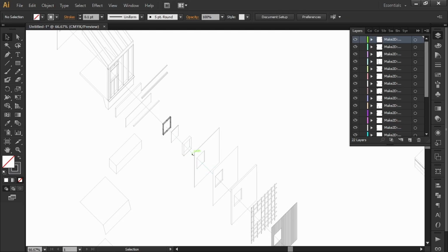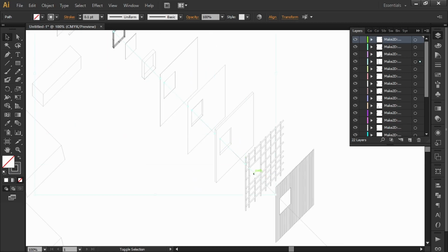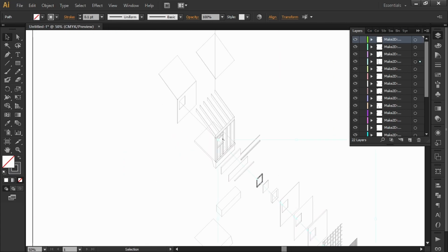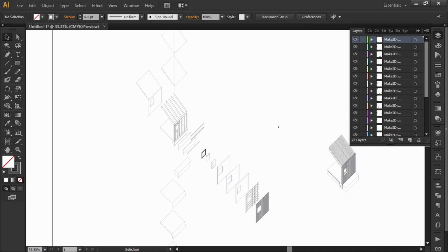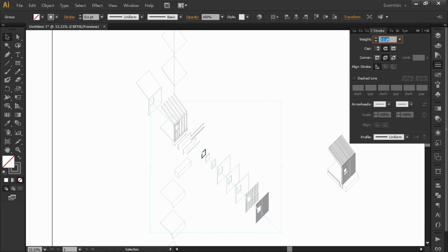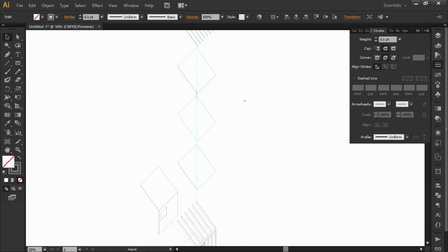So we know, we have these lines here. These lines should be dashed. I actually like to do these lines in Illustrator. I don't like that I took them from Rhino, to be honest. Let me just Control-G, group them, make a new layer, and then we'll say alignment here. We'll do 0.25. We'll make it dashed. We're going to play around and see how it looks. That's good, I would say, for now.